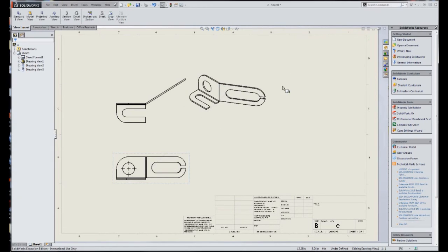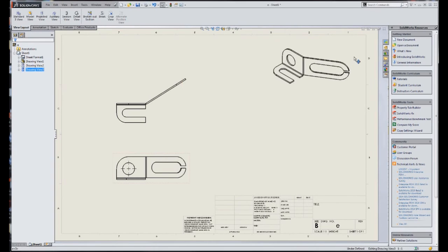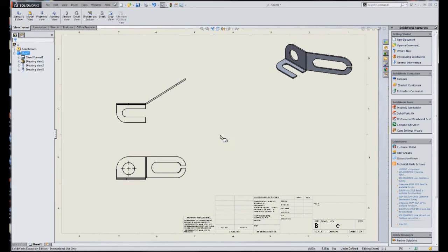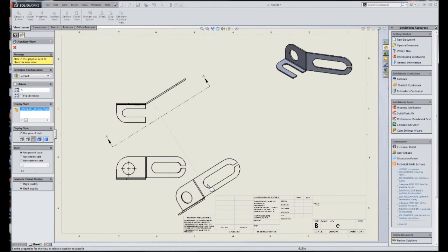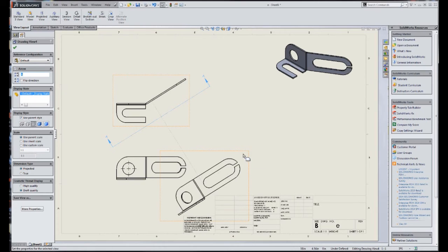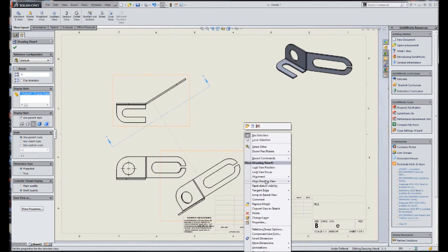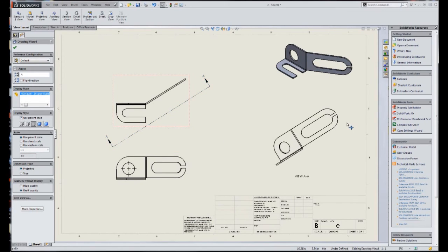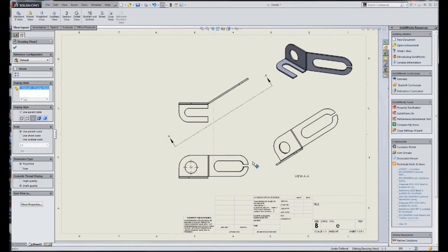But as always, I like putting an ISO in. Okay, I always want the guys to get an idea of exactly what it is they're doing. I like to shade them, as you know. Okay, and we also need information with our auxiliary view. So we're going to import an auxiliary view off of this edge. Okay. So you see it comes way down here. And if I right click in here, I can go into alignment and break it, and now I can put that somewhere in a better spot. And I'm going to drag these over. Okay.